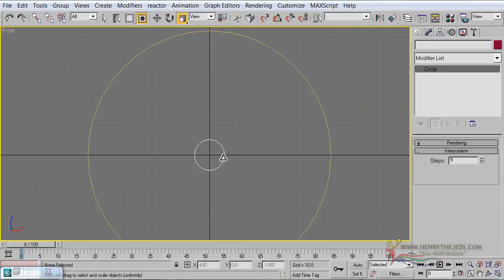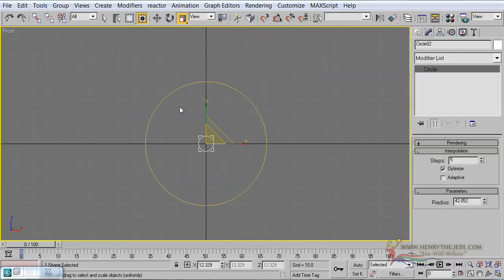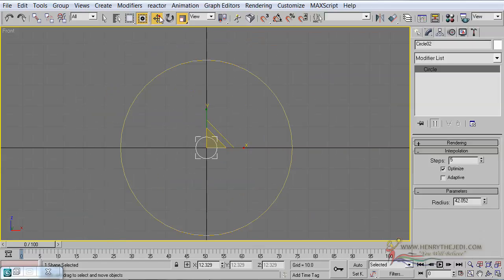Okay, so select this little guy here, and now it's so tiny because I'll need to make up the parts of the cylinders that shoot from. So we can simply reduce the number of the segments, maybe to 5. Okay, remember our aim is always, if an object is not really going to do much work, we simply reduce the number of the polygons. Okay, yeah, let's move on. We are then going to move this guy here towards this edge of the gun barrel.